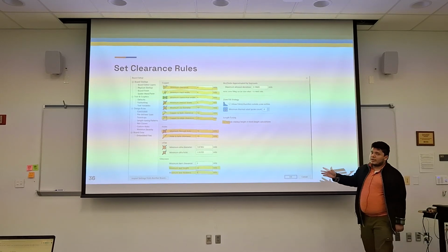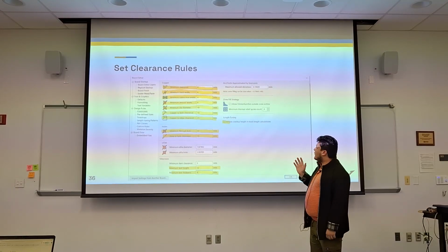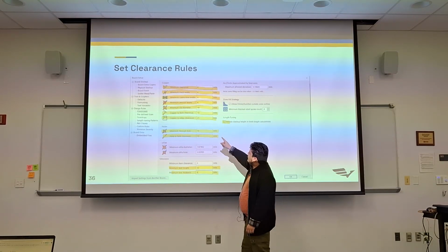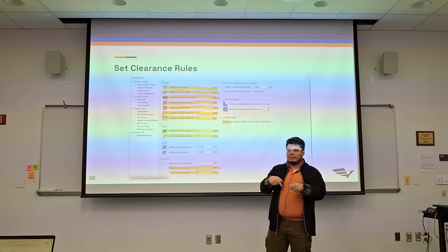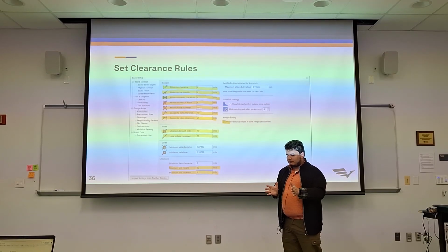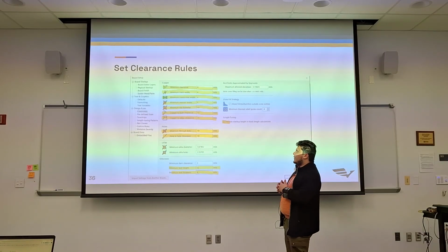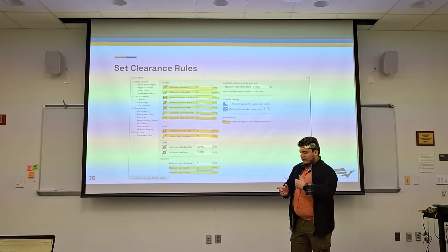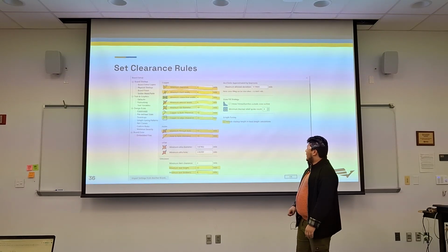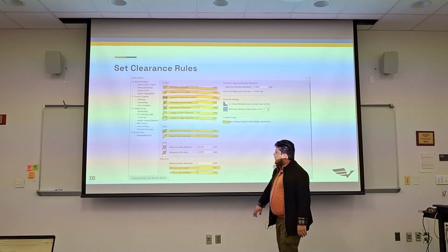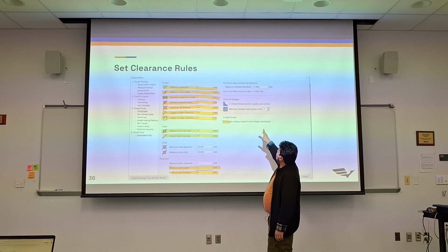And this is where you would set all of these clearances that we just talked about, right? This is a good frame of reference, I think. You always want to have 25 mils copper to edge. That's to allow the routing bit when they're actually cutting out the PCB, like the major edge. That is always plus or minus a certain amount, like 10% or a certain amount of mils. So if you keep 25 mils from your copper edge to the board edge, that is good. And you can set that there, and it's going to take care of it automatically. We're not dealing with micro vias, so forget that. And then your silkscreen, tuning, etc.